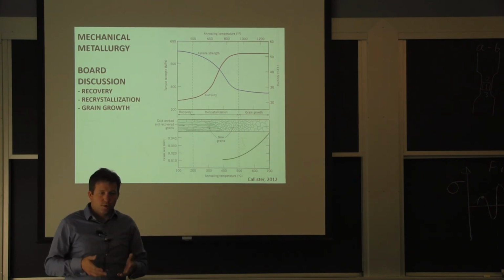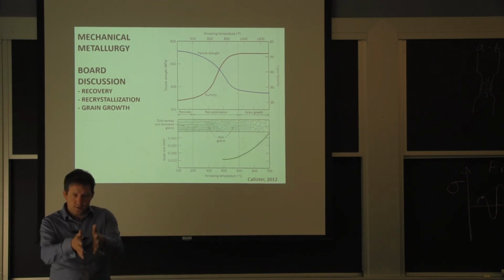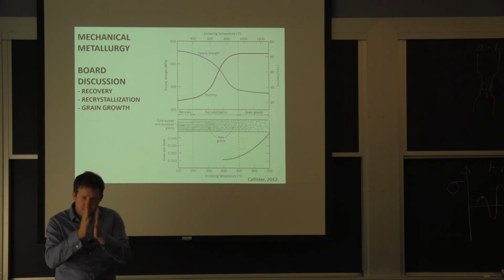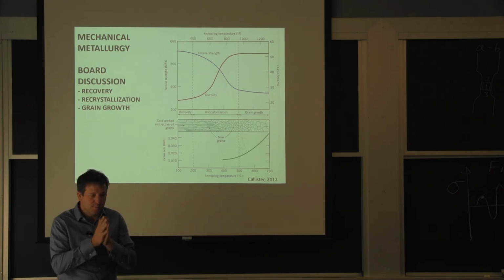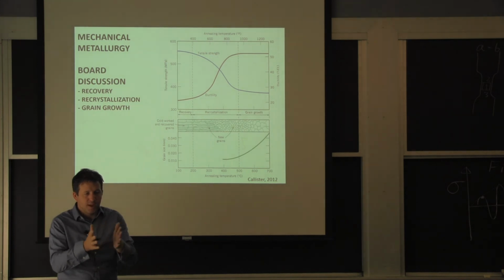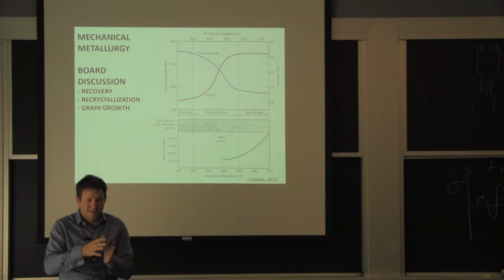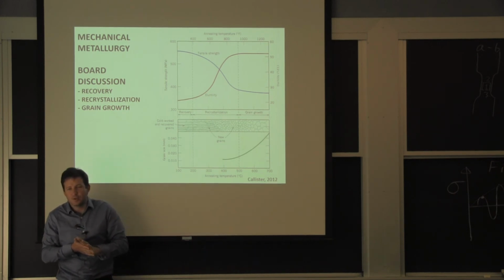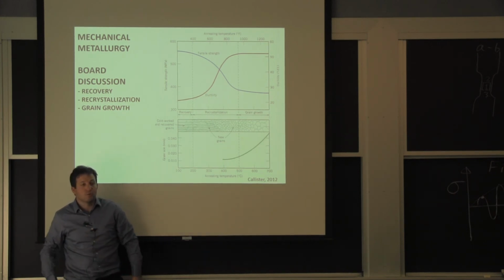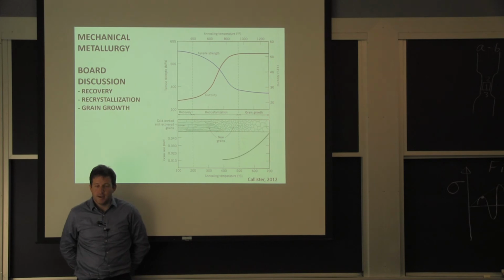When you cold roll and you make a certain shape, let's say I make a sheet, it looks perfectly flat, it stays flat, right? Because there's nothing else going on. If I do the same process warm, when I cool it off, it's going to tend to have some curvature. So the dimensional tolerance on hot rolled products is not as good as on cold rolled products.